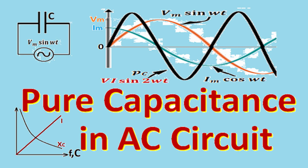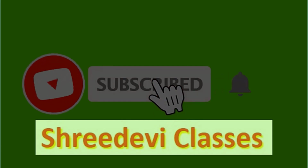By this great learning video, we have explained each and every aspect of pure capacitor behavior in alternating current supply. We have explained how in a capacitor current leads voltage by 90 degrees, and in those conditions average power of the capacitor circuit becomes zero and power is only reactive power, which results in storage of energy when voltage is increasing and release of the same energy when voltage is decreasing. We have also explained the variation of voltage and current for the entire cycle of the capacitor in great detail, so that you can understand this concept with great clarity and ease.